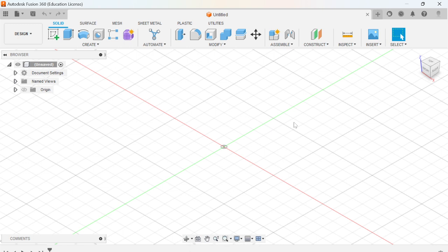So trackpad or not, there is one solid universal way to move around the program, and that is up here with what looks like a little cube. This is called the view cube. Any 3D object has 6 sides to it. You can look at your laptop, your phone, hat, water bottle. There's a front, back, left, right, top, bottom. And if you look at the cube, that's exactly how it's labeled. Every 3D object has 6 sides, and this cube allows you to differentiate what side you're looking at, and it allows you to move and pivot between them.